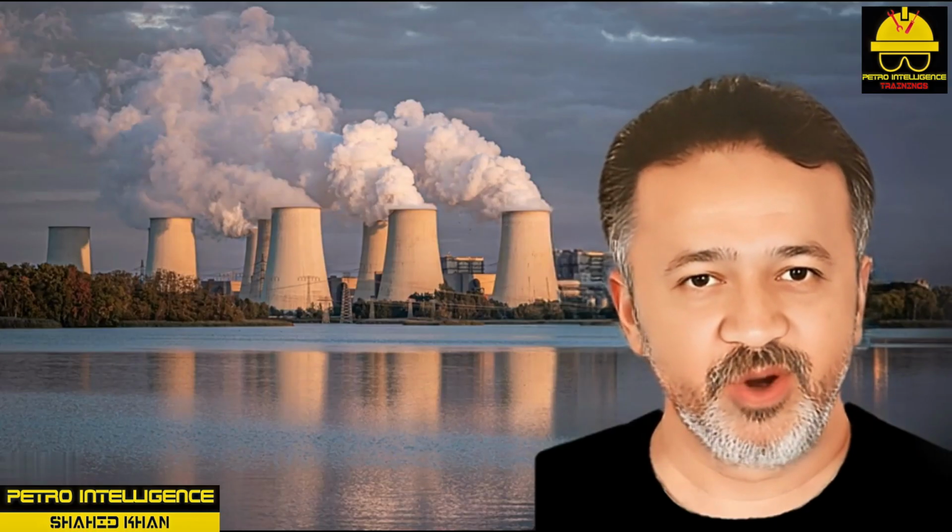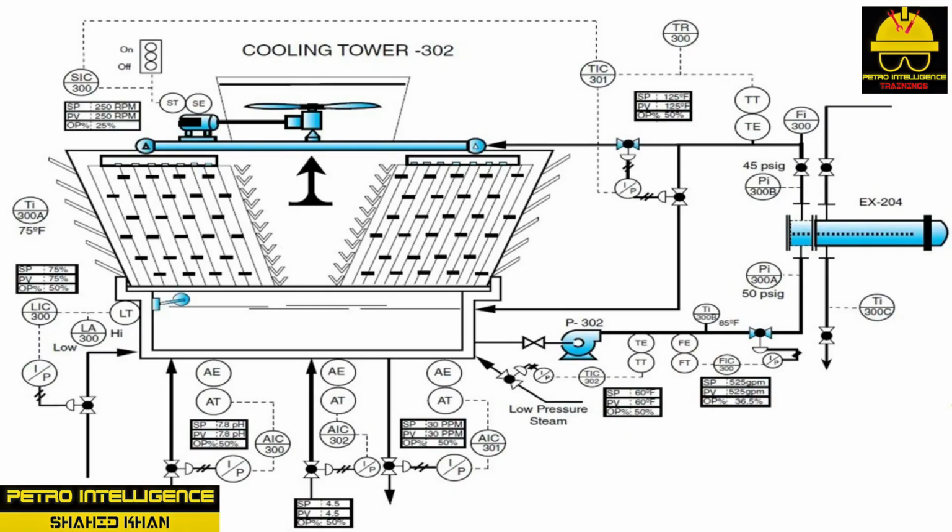Cooling tower 302. CTW302 is an enclosed structure with a system of air louvers designed to direct airflow across the fill. As warm water enters the top of the cooling tower, the water distribution system carefully sprays or directs fluid flow over a labyrinth-like honeycomb, splashboards, or fill. The purpose of the fill is to allow the hot water to spread out over the surface of the boards.